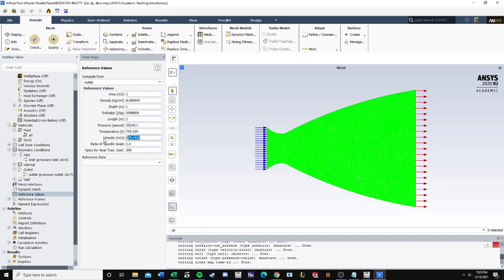And the desired velocity, or the velocity calculated for the exit, was 2,447. And that was getting 548 for the speed of sound and times 4.46 for the Mach number that I expected at the exit. Don't think I need to change anything else.